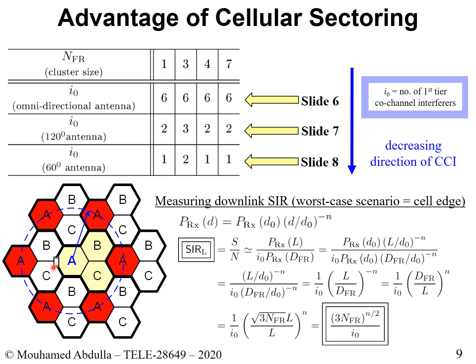However, this could be a bit tricky and it could take some time to do the analysis and the math and all that. But what you can do is use the distance from these points, these co-channel cells, to the center of your cell. So this is not really what you wanted to get. You are interested to measure it at this point, but you already have the distance up to this point. So you could use that, and instead of saying it's going to be 100% accurate or exact, you could just use an approximation, because you'll get a measurement of your aggregate interference, and it's going to be a reasonable estimate. And therefore, we use this expression here because we're estimating.